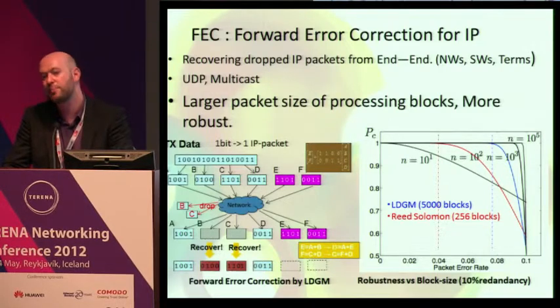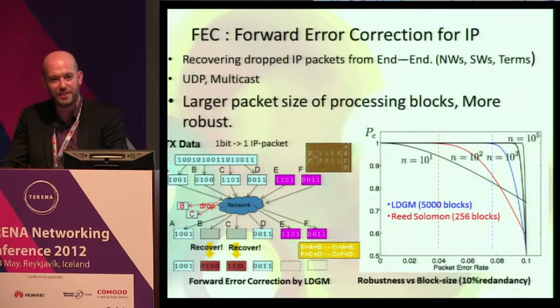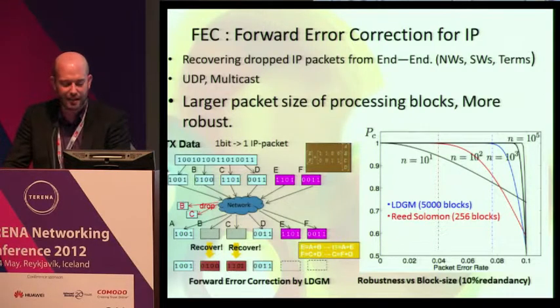This is scaled up dramatically, and these packets, A, B, C, and D, are increased in size because of the relationship between the larger packet size making it more robust. And this creates a forward error correction system that can actually cope with 10% packet loss before the signal degrades, which is very impressive. And luckily, we've never had to actually use the full 10%, but it's impressive nevertheless.